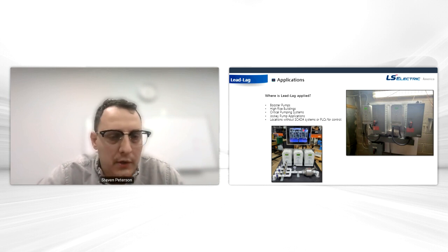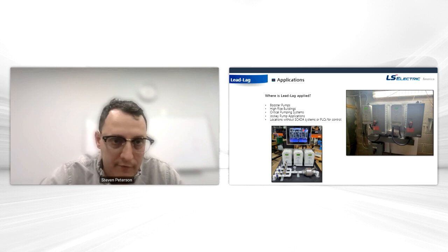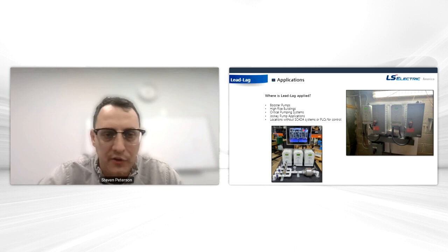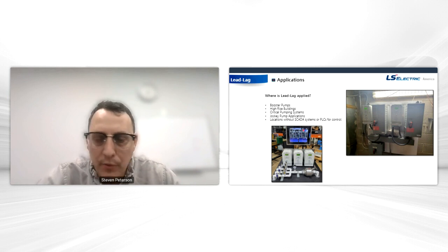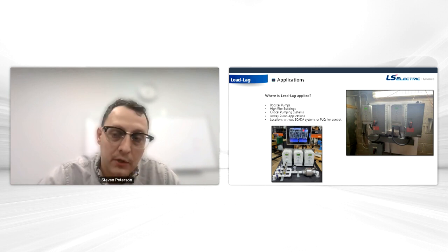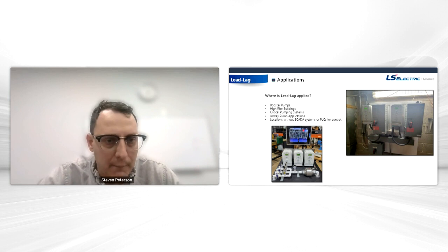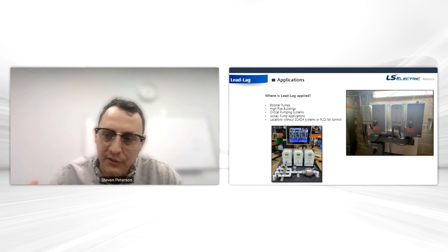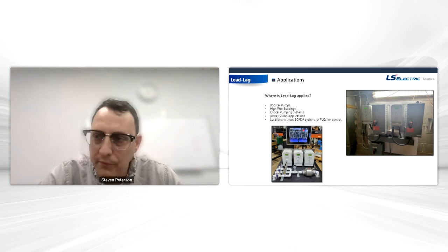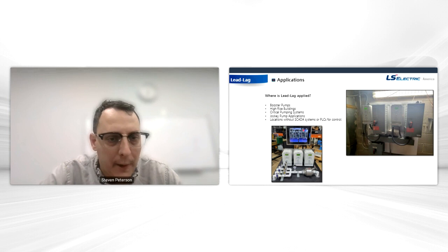All right, so the last thing I'll mention about lead lag is where it is applied. Firsthand, I've helped out with a lot of lead lag setups. We've had this lead lag capability for quite some time. The more people that learn about it, the more people end up using it because, again, you don't need a PLC. It's all built into the drive's firmware. So we commonly do these on booster pumps, high-rise buildings, taking city pressure and boosting it up multiple floors. Critical pumping systems where you need redundancy. We can't have this drive go down, we need another one as a backup. We do those all the time.